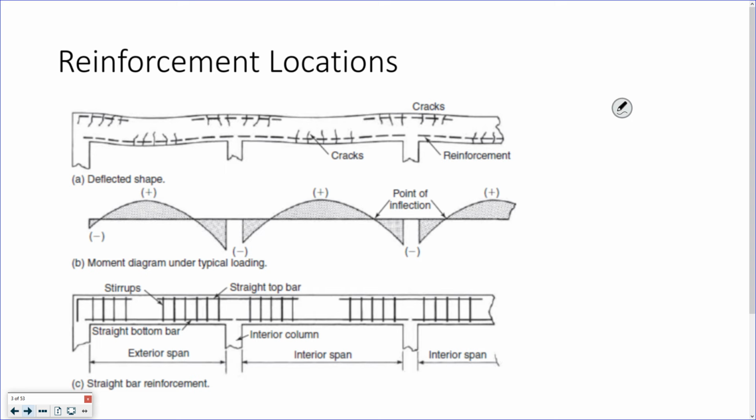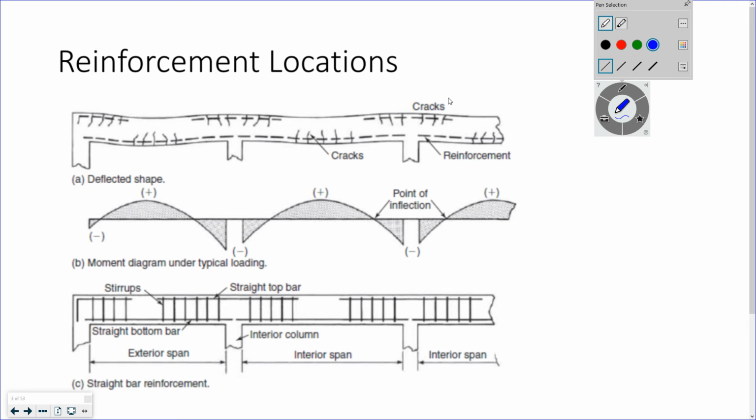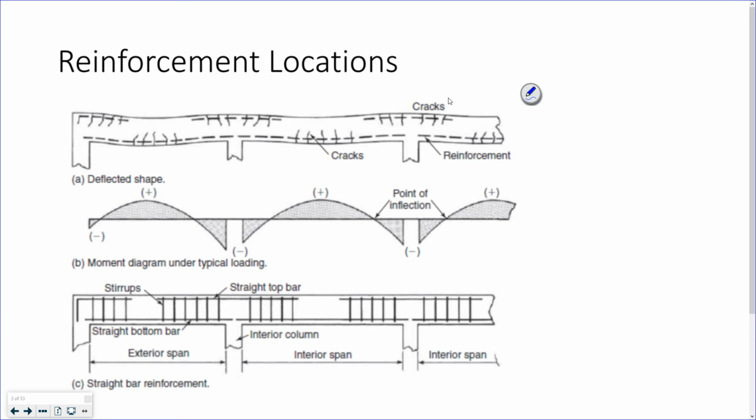Now what you'll notice is you don't necessarily need continuous tensile reinforcement, right? If the moment gets small enough, if the negative moment gets small enough here in the middle, you don't need the reinforcement to go along the entire length, right? That you can save money because materials cost money, right?